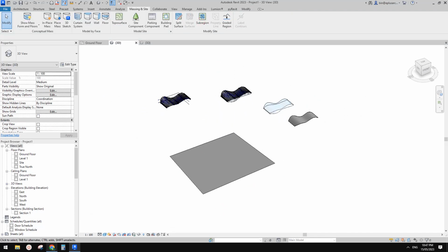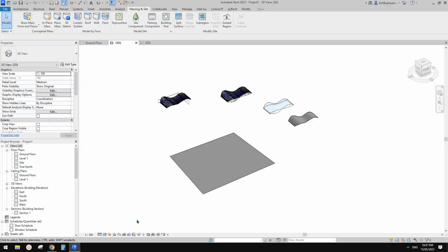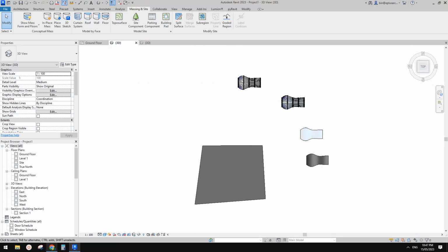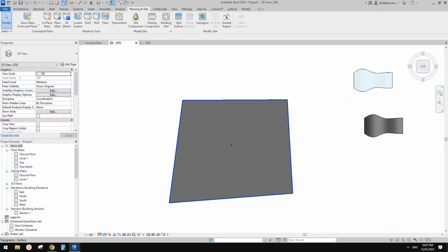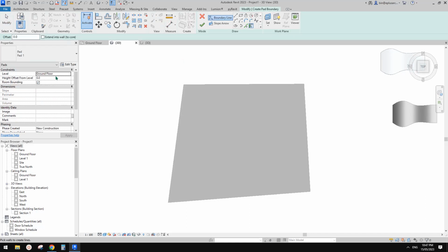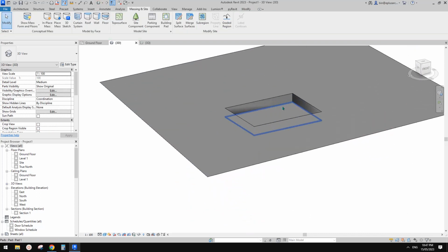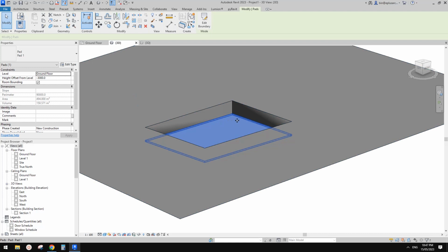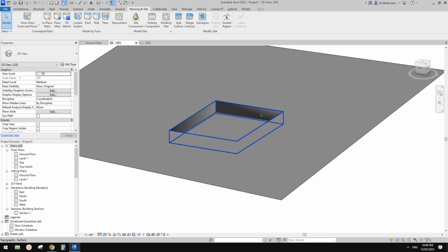So usually what we do for a quick schematic stage project, when we need to do those underground, we just use a building pad. So for example, I'm just going to place a building pad, maybe 3 meters below ground. So I just draw a shape and finish. So now if I go to 3D view, you can see that. So this will place like a floor. So it's a building pad, but it's like a floor onto this top surface, and then this will adjust the